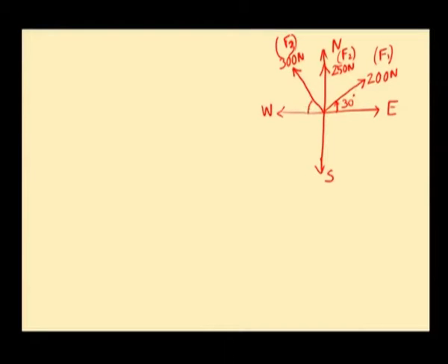The inclination of this force with respect to west will be 45 degrees. Also the inclination of this force with respect to north will be 45 degree, because this force is acting along northwest direction. Finally, the fourth force is 350 Newton inclined at 40 degree to south of west. So, 40 degrees measured from west towards south. Magnitude of this final force is 350 Newton.